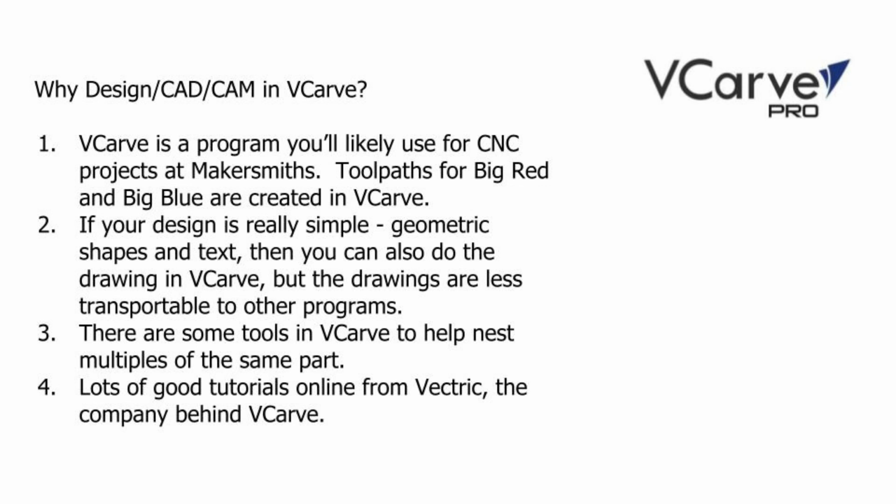So when are you likely to use VCarve in your projects? As a Makersmiths member, you're likely to use it during the CAM part of your project, in other words, when you're setting up your toolpaths. There's a computer at each space that has VCarve installed so you can export your G-code with the correct parameters for running your code on either Big Red or Big Blue.